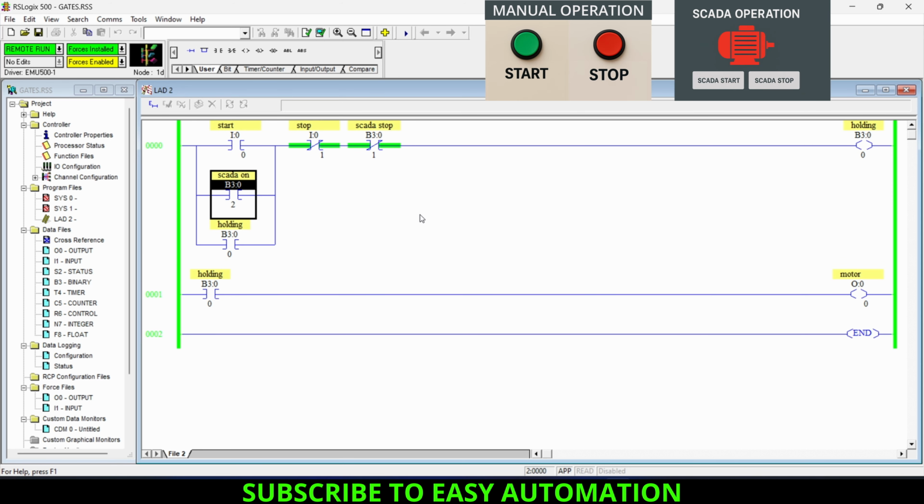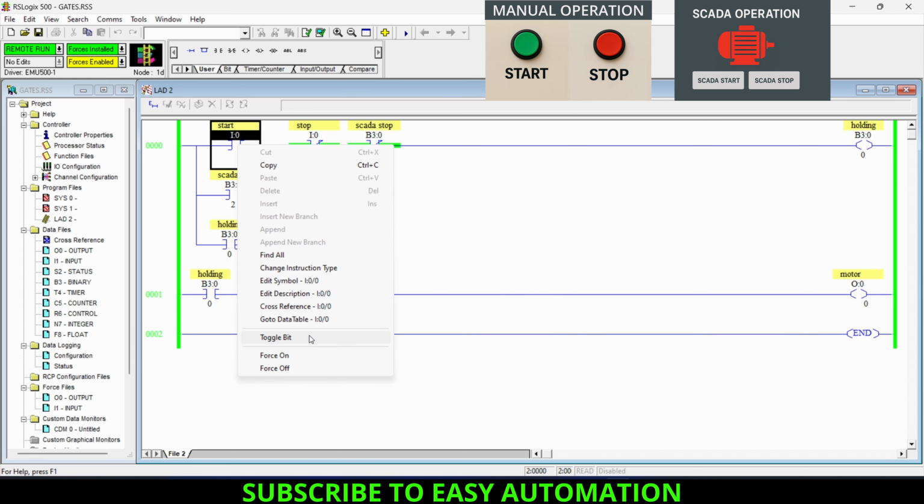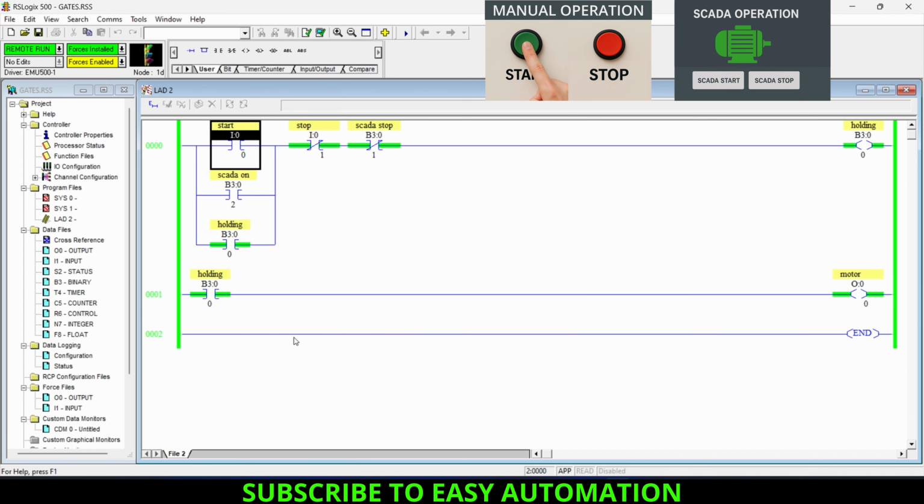Let's consider our first condition in which we are going to operate our motor from manual operations, like from the push button. So imagine this start is the push button and I will push it on and release it. Then our motor is on, and if I want to turn off this motor by another push button, I will push this button on and release it. So our motor will turn off here.